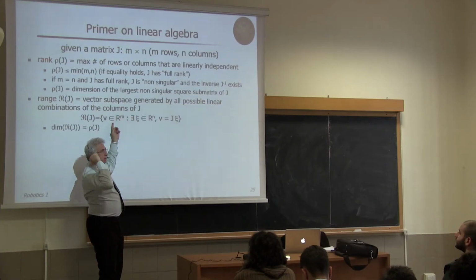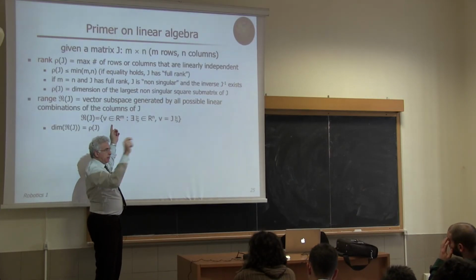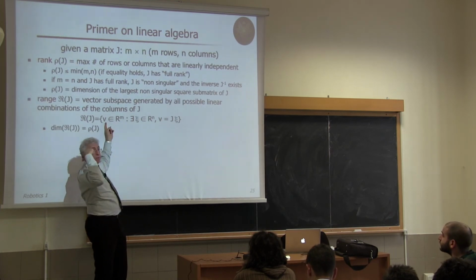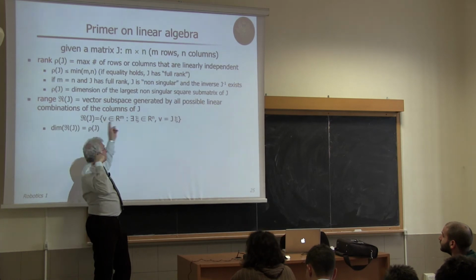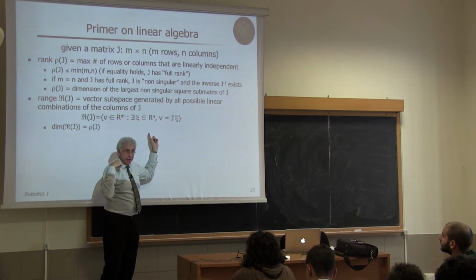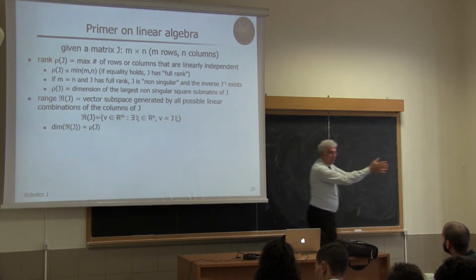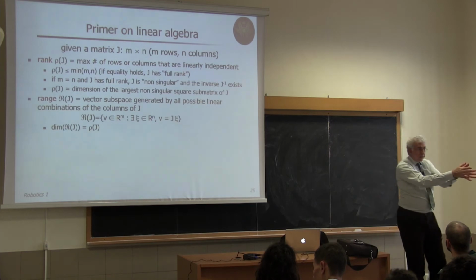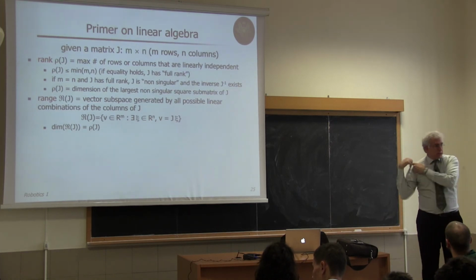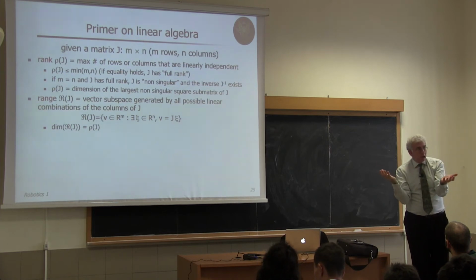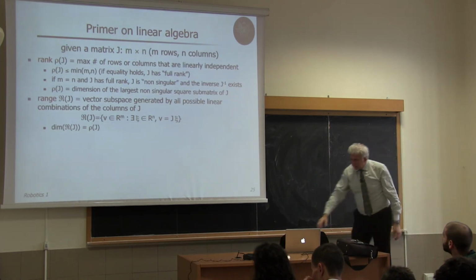Think about joint space and Cartesian space. So all vectors in the Cartesian space that can be generated with some vectors in the starting space, which is the joint space. Okay? So it's very important to understand if I can generate some Cartesian velocity when I'm in a given configuration by some joint velocity. And this space is the range space of the Jacobian.